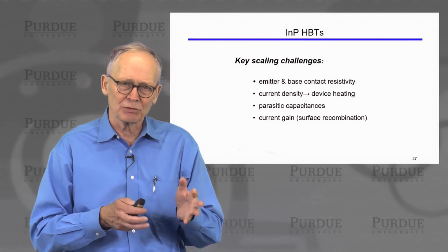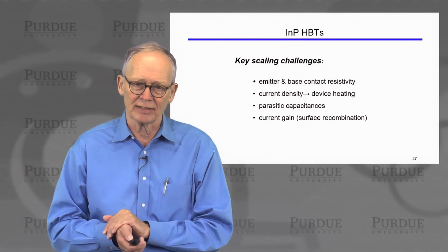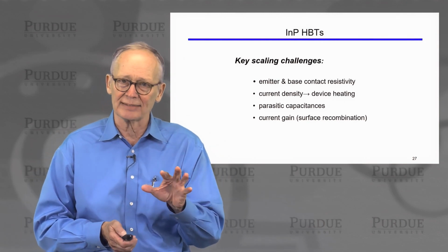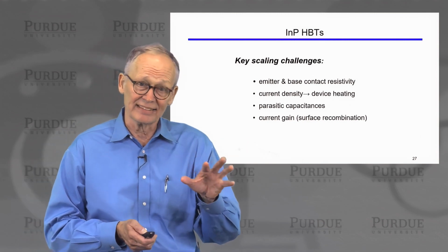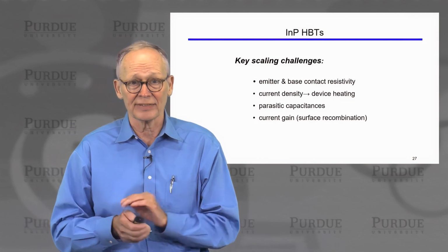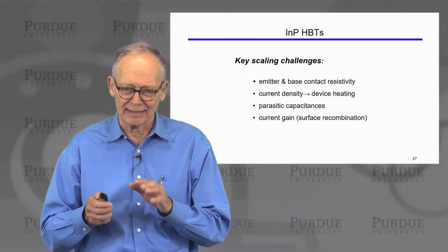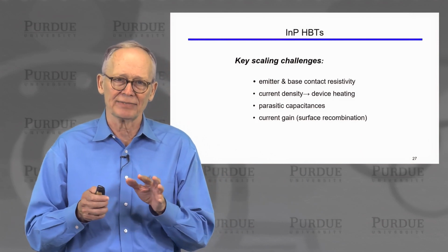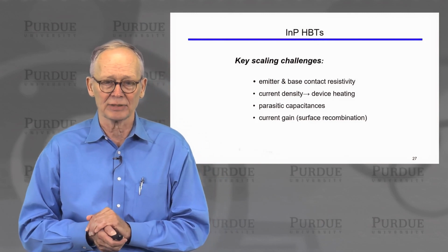So if I think about these indium phosphide HBTs, some of the key challenges are the contact resistivity, because we operate them at very high current densities. That leads to some device heating issues, so we have to carefully consider the thermal effects in these devices. Parasitic capacitances are a constant struggle: we must minimize their effects so that we can push to higher and higher frequencies.